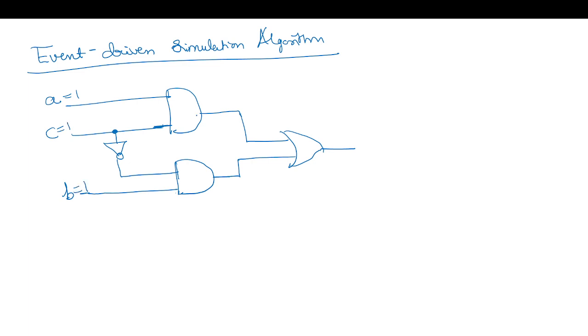For the first simulation, let's just consider some delay values for this circuit. So this will be 1 after 2 nanosecond delay and this will be D equal to 0 after 2 nanosecond. I represented F, which will be 0 and 1 is 0 after 4 nanosecond, and G will be 1 after 2 nanosecond. So now this is the initial state.